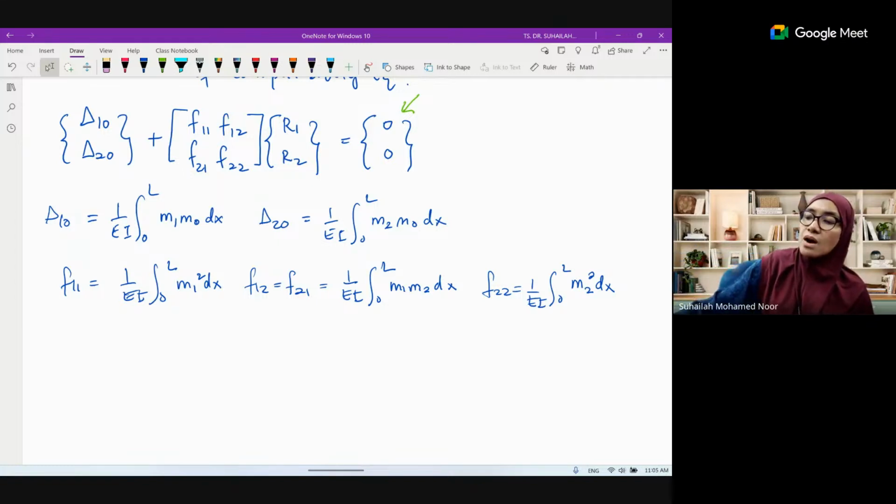So these are all 6 displacements. Why do we calculate these displacements? Because we want to fill in the compatibility equation. The redundants are there, so our problem is with the redundants. Remember we want to calculate 5 unknown reactions, and we cannot calculate all 5 directly. So we have to divide them into 3 and 2. The 3 can be determined using equilibrium equations, and the 2 we determine from the compatibility equation.